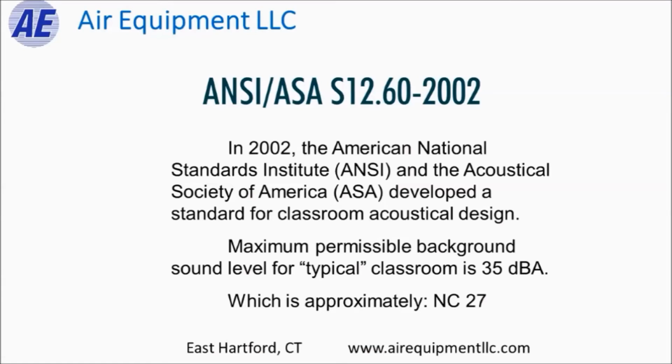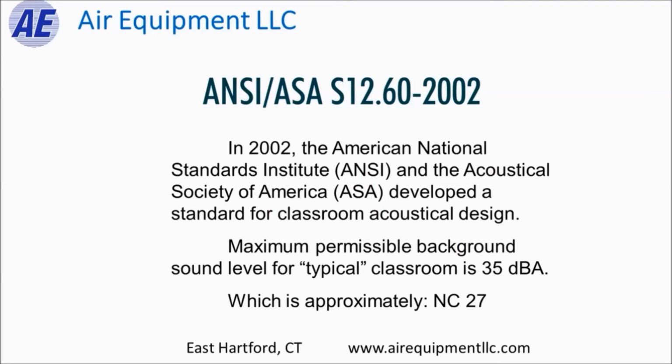Back in 2002, the American National Standards Institute, or ANSI, worked with the Acoustical Society of America to develop a standard for classroom acoustical design. And this standard is S12.60-2002. What this standard said is that the permissible background sound levels in a typical classroom setting cannot exceed 35 dBA. Now, dBA is another system of presenting a single number to give us a weighted average of sound pressure levels. It's similar to, but not the same as, the NC. And in fact, the 35 dBA mark is approximately an NC 27.